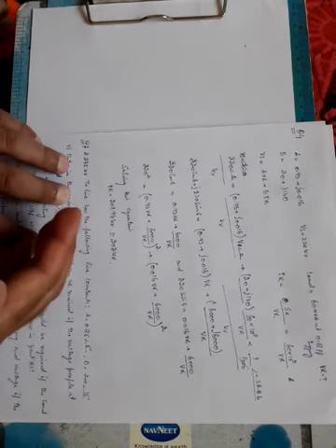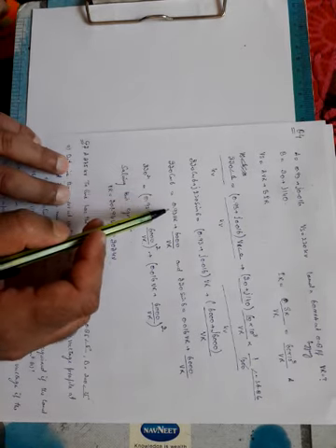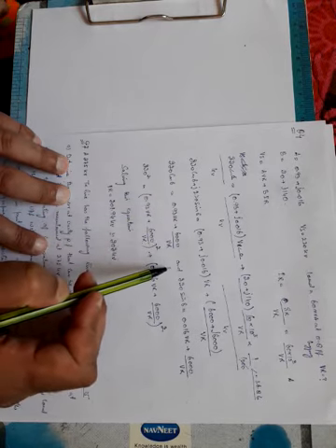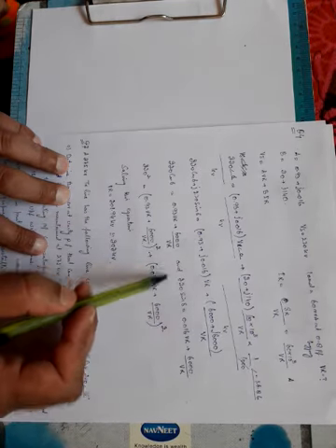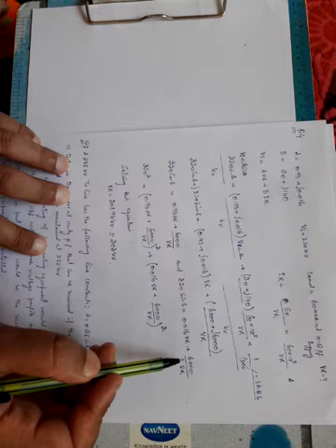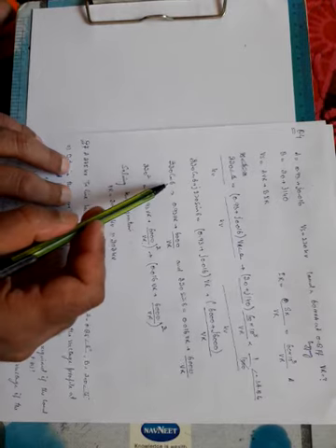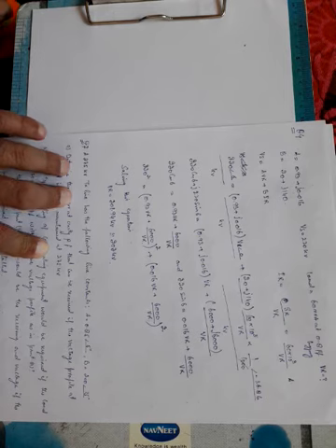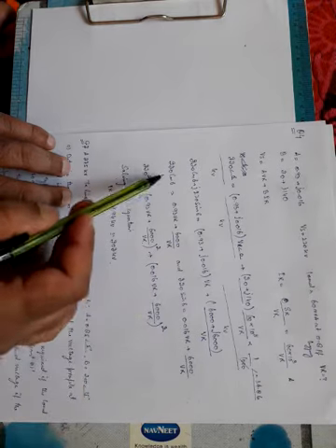Now equating real and imaginary parts, in this case 220 cos delta is equal to 0.93 VR plus 6000 divided by VR, and this is the real part. And 220 sin delta, this imaginary part, is equal to 0.016 VR plus 6000 divided by VR. Actually these are two equations with two variables, because one variable is delta and another variable is VR. We are only interested in the value of VR, so we will eliminate this delta. How will we eliminate it? We square and add these two terms.